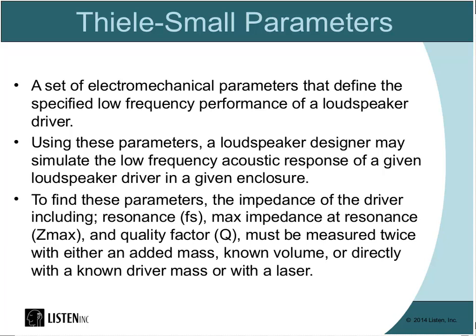So if it's a big speaker, like a home speaker, you can probably get away with added mass. If it's a micro speaker, good luck. First of all, the mass of the diaphragm is probably so small that you're going to have a hard time putting a mass that you can weigh on it. You might not even be able to get into the volume to even put it there. So typically for micro speakers, people use known volume.